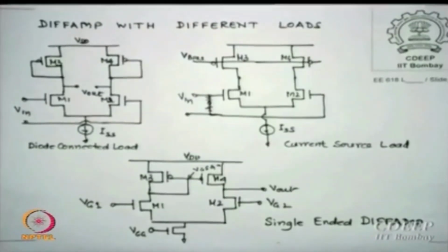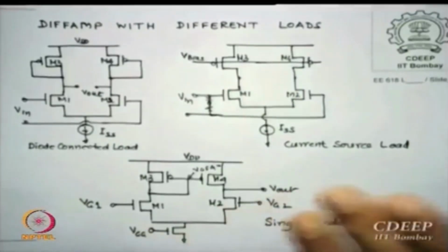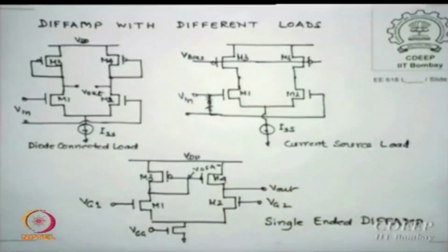Gate is connected to drain, so the device acts like an actual diode. What is the difference between this diode, this is also a diode, and a normal diode? Do you know what is the difference? The diode has an IV characteristic which is exponential, is that correct? In all CMOS technologies there is no real diode made, actually a diode is this, okay.